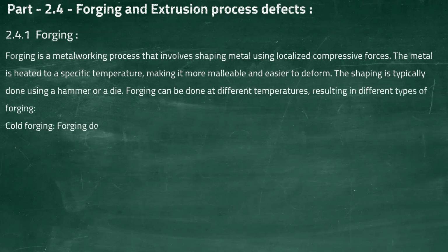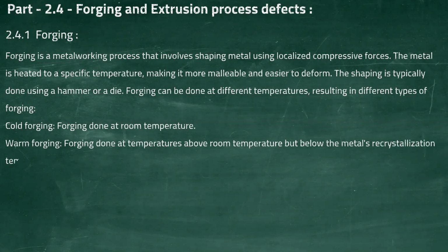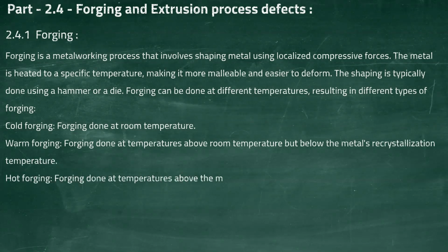Cold forging, forging done at room temperature. Warm forging, forging done at temperatures above room temperature but below the metal's recrystallization temperature. Hot forging, forging done at temperatures above the metal's recrystallization temperature.